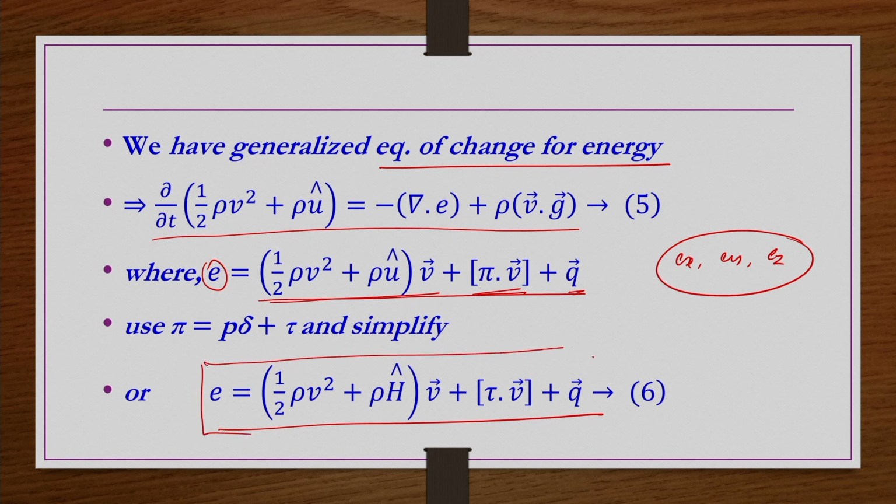So, this we are going to simplify for the given problem, because the energy equation directly in the temperature form we cannot write. Why can we not write? Because in that form, the viscous dissipation term that is there is not for power law fluids; it may be different. For non-Newtonian fluid it is incorporated in a different way. How different, we can understand from here only, because this term is going to play a leading role now because of non-Newtonian rheology, and this is directly not available in the energy equation in the form of temperature. So, the same equation is written here also.